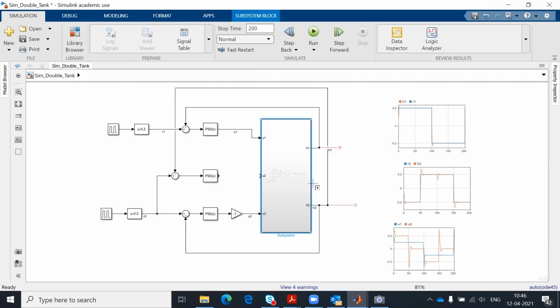It's actually the case in MIMO systems. If we want to design a SISO controller, because the controller you have here is SISO, you compare the output with the set point, and the error will change only one input. In case of a MIMO controller, you compare both outputs with the set points, and both errors, so this error can change the other one, and the other error can change this one.